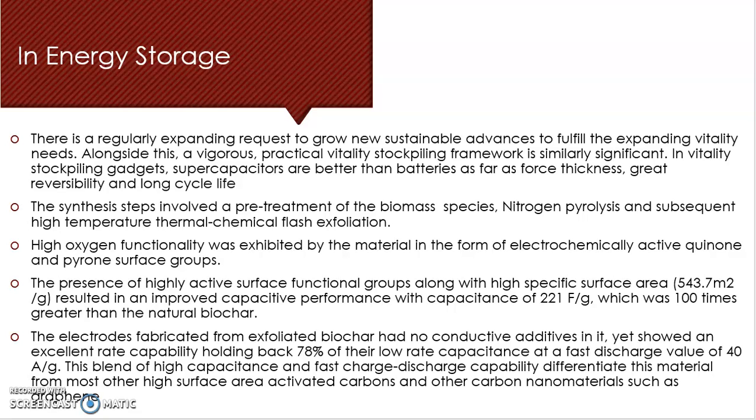The presence of highly active surface functional groups along with high specific surface area, which is 543.7 meters square per gram, resulted in an improved capacitive performance with capacitance of 221 farad per gram, which was about 100 times greater than the natural biochar.